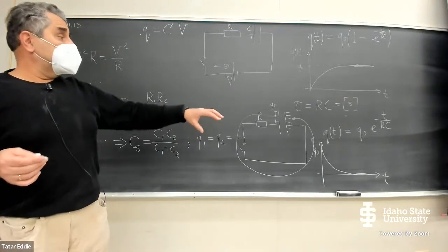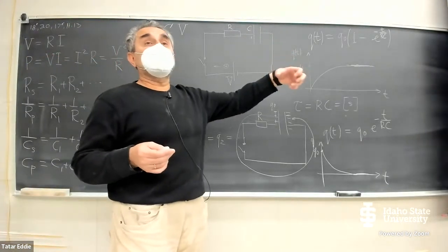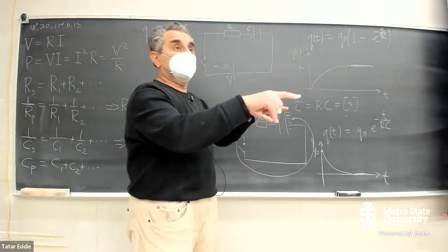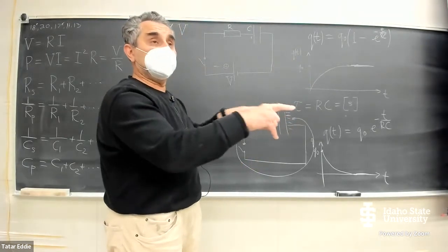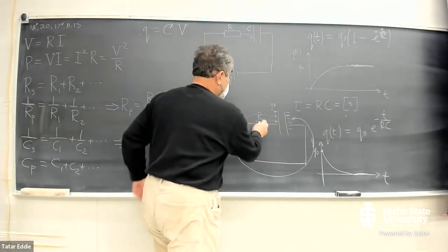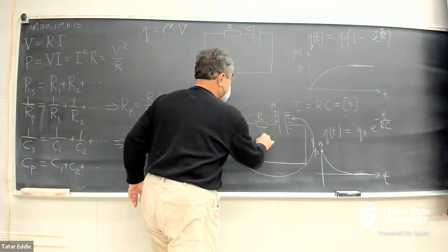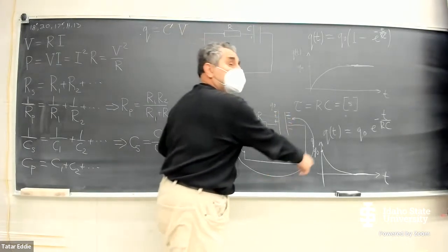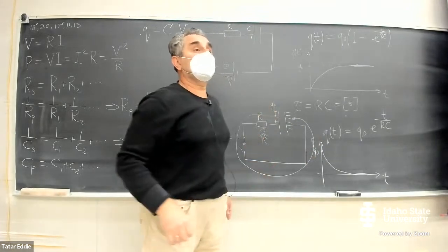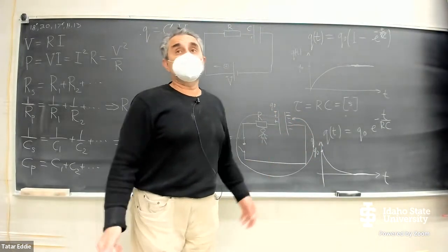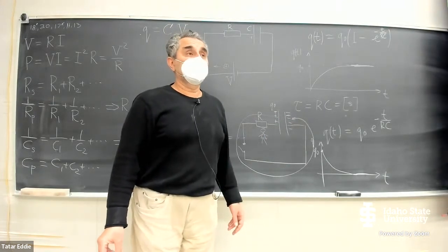So if somebody grabs this charged capacitor and touches the two terminals, the two plates of the capacitor, well, in that case, the body of the person is like the resistance here, and the capacitor is going to discharge through the body of the person that holds the two terminals. And this person is going to feel it, right?